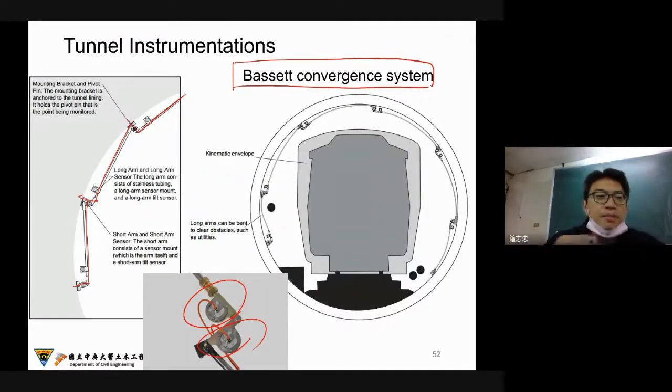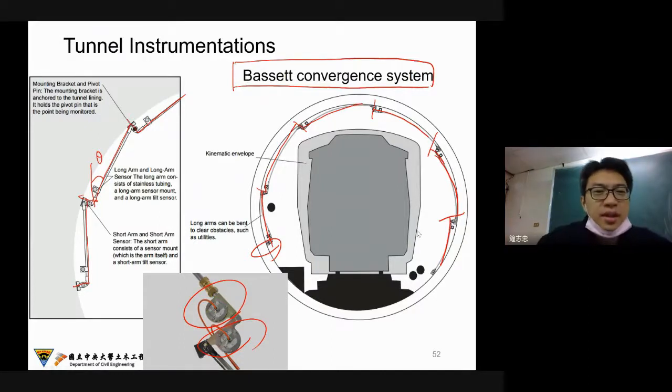So you can measure the incline degree, I mean, the theta between the gravity direction and the incline direction. This is just like the inclinometer. If you already have a fixed end, you can calculate the shape of the convergence system. I think this is very unique, especially for tunnel monitoring.